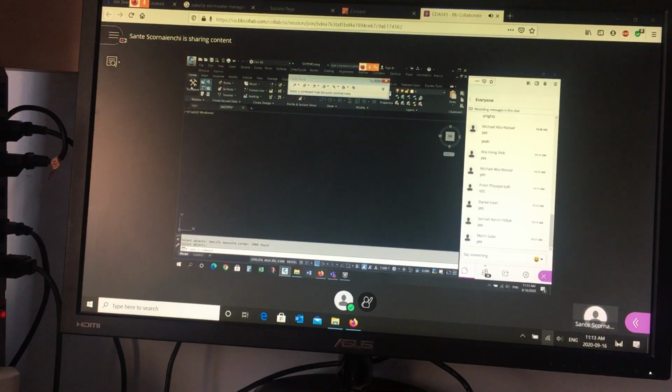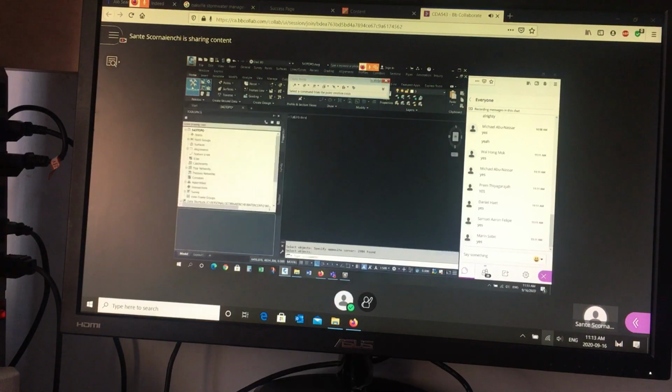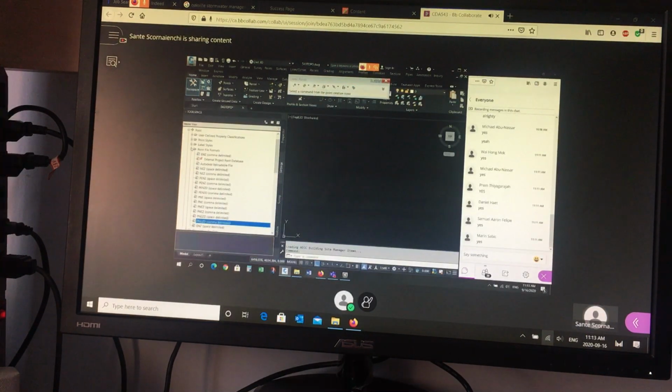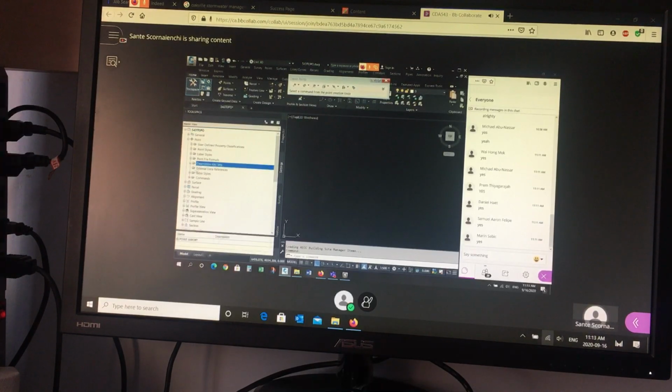So you need your tool space. You need to go to settings, and then in settings for this file, you need to go to point, and then there's something called description keys. Now I've already created the one you need to do, but I'm going to show you a couple. Now what are you programming? This is where you need to explore the data you're provided. That's why you want to open up that CSV file.